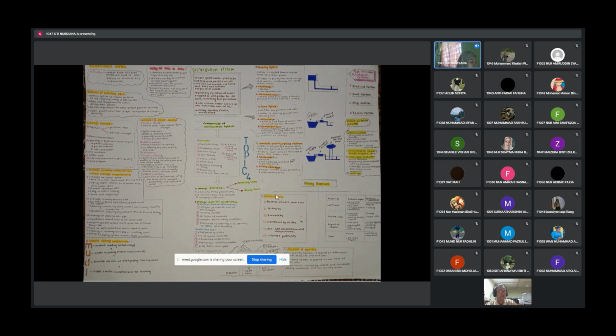There is a method of reducing NRW, and there are leakage factors, which are pressure, ground movement, rusting in pipe from electrolysis, soil condition, traffic load, material and water, and pipe lifespan. Leakage. And then for leakage measurement procedure, there are 2: direct leakage measurement and indirect leakage measurement.